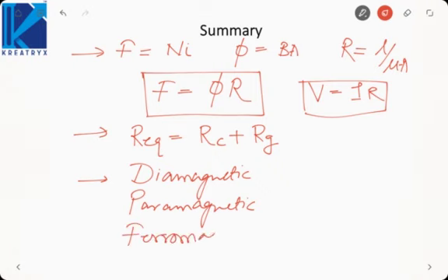They have residual magnetism and dipoles are oriented in the same direction as the magnetic field, so they will be strongly attracted. They have strong magnetization. And last we saw ferrimagnetic, in which dipoles are oriented in opposite directions. So net magnetization is small, but these are preferable because of higher resistivity, so reduced eddy current losses.